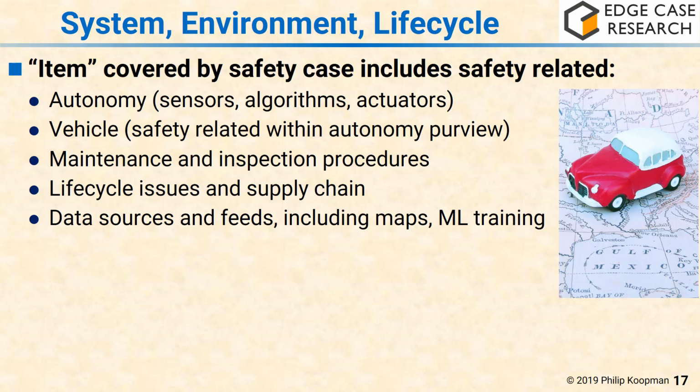So for example, if you're going to say, well, we have run flat tires, what happens if someone replaces with a normal tire that's not run flat? Now, that's not a requirement for the autonomy to figure that out, but the safety case has to argue either we're sure it'll never happen because, or if we do get a blowout, despite the fact the tires are never supposed to blow out, or the wheel comes off because somebody forgot to bolt it on properly, we're going to do the right thing, or it will happen so infrequently that it's okay to take that risk.